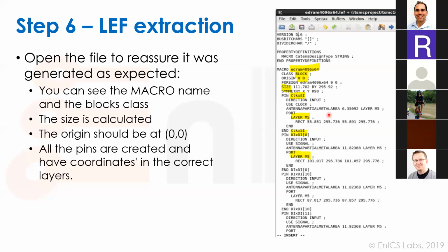What I'm saying is, if your antenna information is correct in the LEF, you should have no antenna problems at the end of placing. Exactly. But we didn't know that until the day we were supposed to push the button on sending out the tapeout. Slava thought it looked weird that there were so few checks on the report.